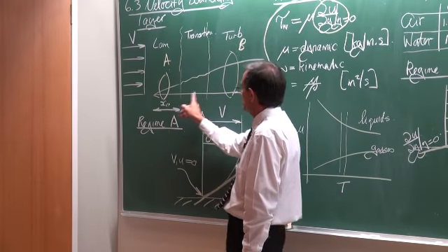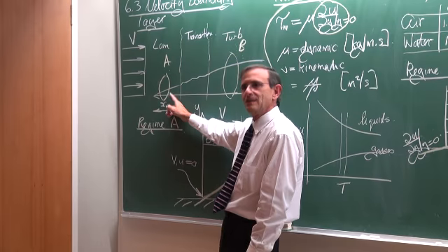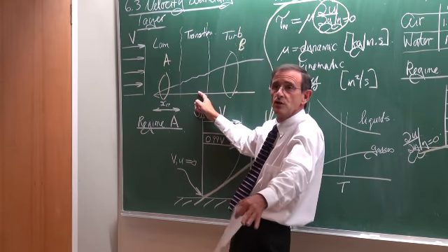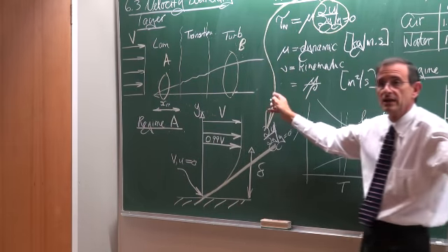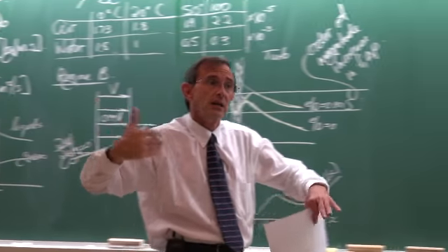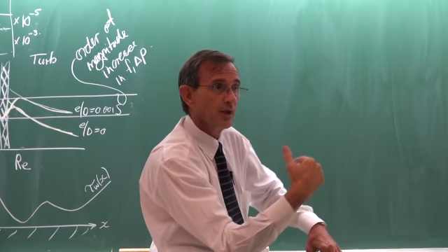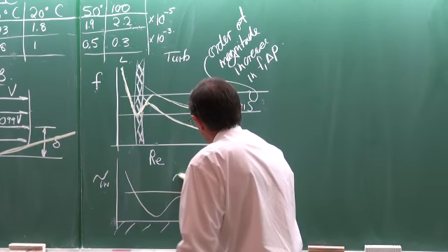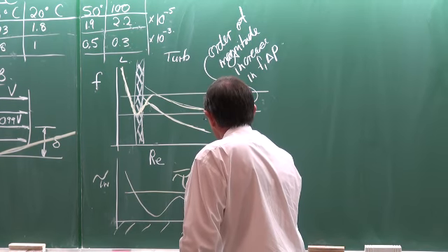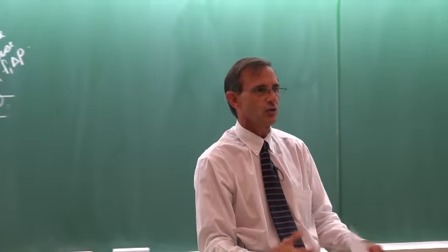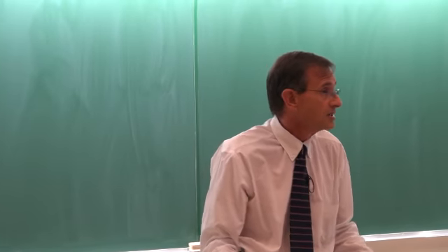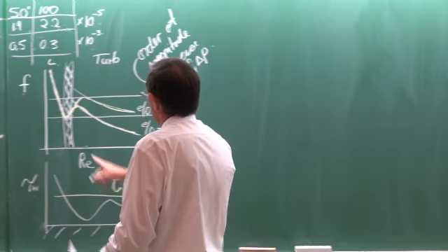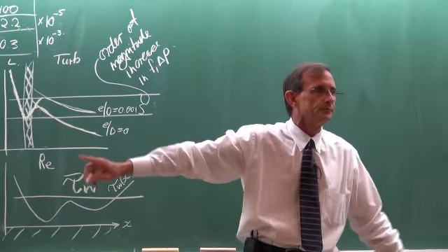If this velocity gradient changes, the shear stress should change. It goes through the transition flow regime and then the turbulent flow regime again. So the shear stress changes as you go downstream along the plate. As engineers, in most cases we are interested in the average. If we have the average shear stress or the average drag, then we can design something with it.